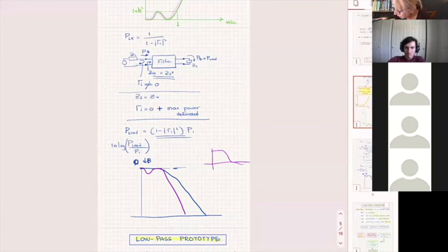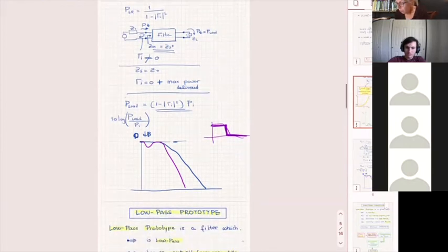Ideally, if I could, I will have a low pass filter that looks like that. Like a pulse. It sends everything through at low frequencies, and at some point I cut everything and nothing goes through. Well, it does not happen really like this. So the fastest you can reject in the rejection region, the better off you're going to be as a filter. And that's why the Chebyshev is a good design, because it gives you this.